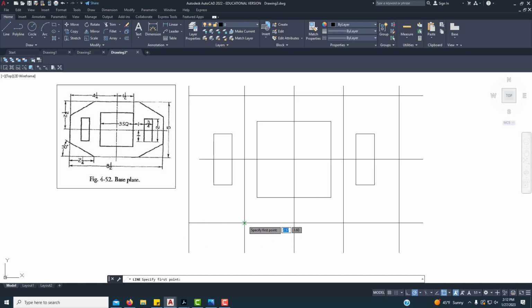We're going to click on this intersection, and we're going to move our mouse. Now I want you to look at what the angle actually says in AutoCAD. If we have a polar angle, then if this is 90 degrees at the vertical, and then we look at the horizontal, this is 180. We need 30 degrees up from the horizontal.